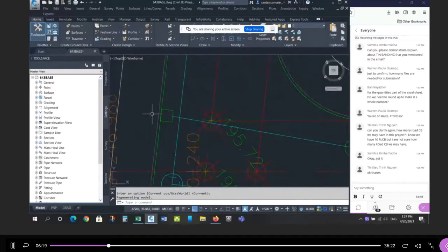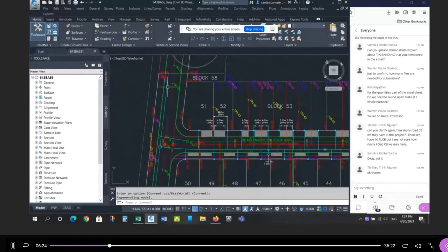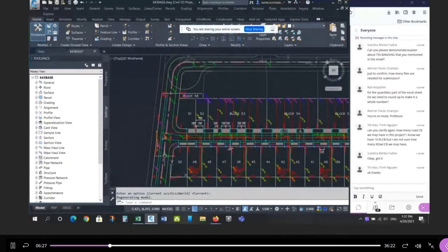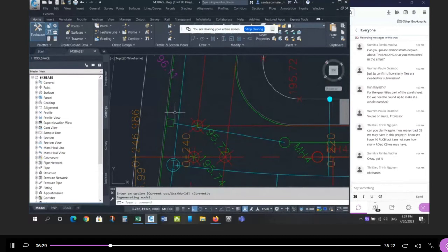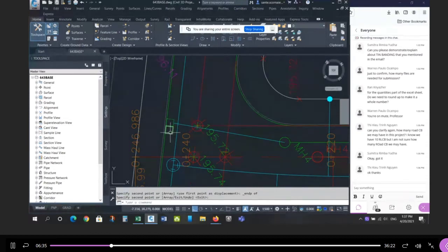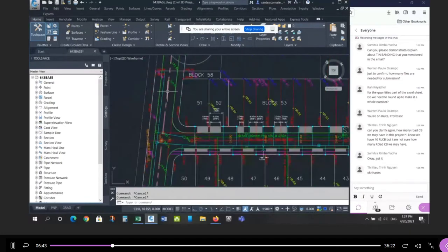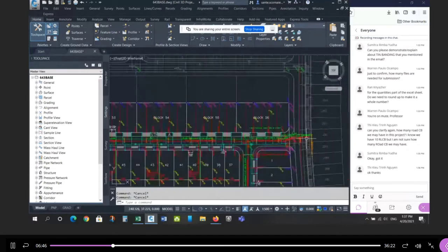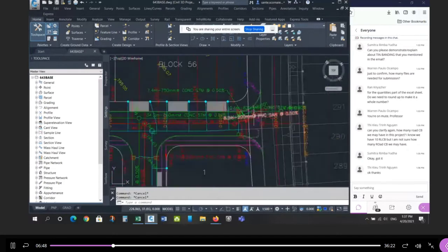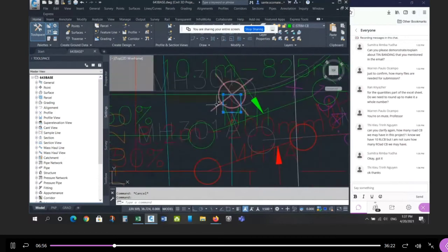So if you zoom in here, some people, because there's a standard, I forget the number, there's water coming from the high point in this direction and from the high point in this direction. So this is actually receiving water from both sides quite a bit. So some people actually put in a double catch basin, where the middle is right on the low point, like that. So you could put a double there because of the area that's coming on this side and this side. Here, there's a low point, but remember what's happening: this road is falling and coming into here, and this road is falling and coming into here. So this one may want to be a double catch basin.